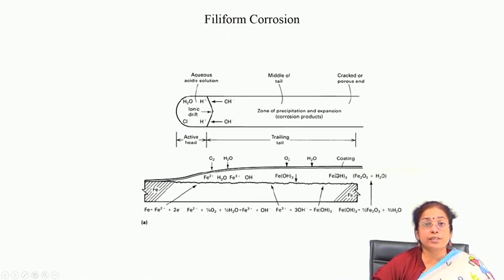Whenever there is hydroxide formation, there will be much more moisture absorption. So, there is always a differential aeration cell formation, and also different phase formation like microgalvanic cell formation, because hydroxides are more stable as compared to the iron which is there. As a result, because of the galvanic cell formation and moisture absorption, this reaction proceeds from one side to the other.